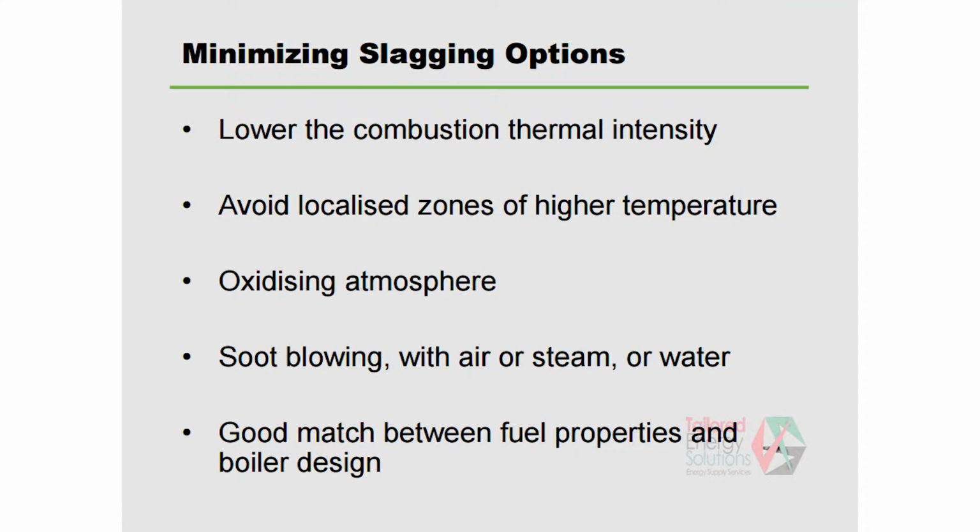How to minimize clinker formation? If you are burning very intensely and the combustion temperature is too hot, obviously you get more chance of clinker. You need to avoid localized hot spots so that the temperature is more even and the heat is dispersed properly.